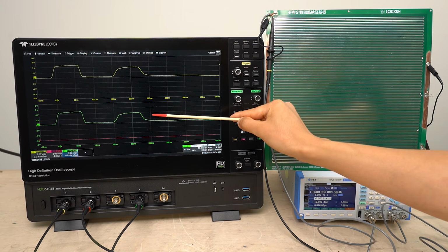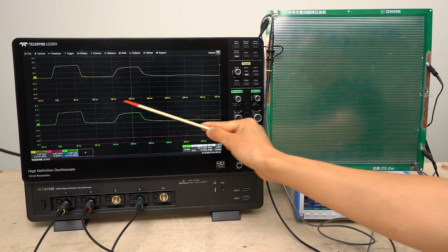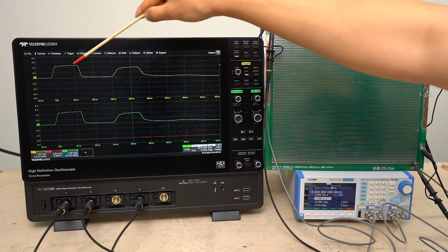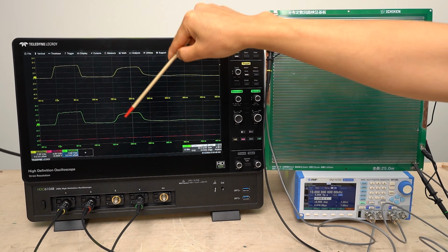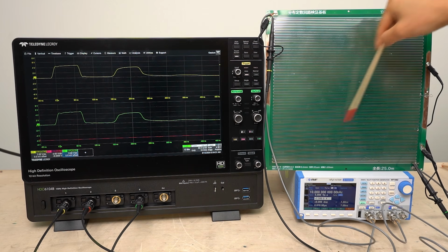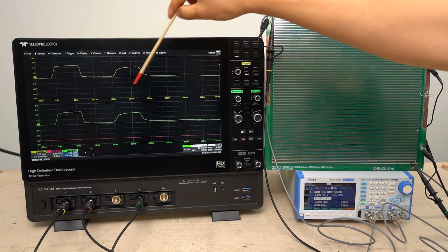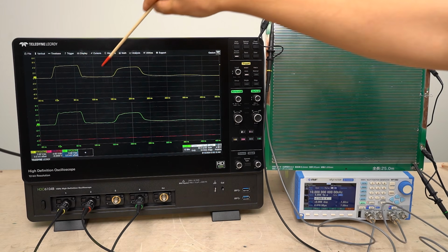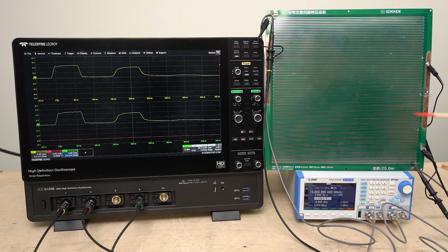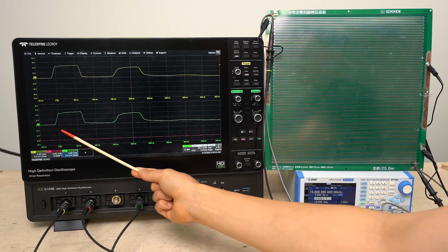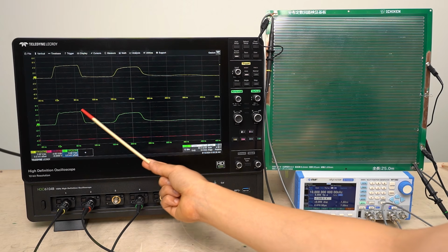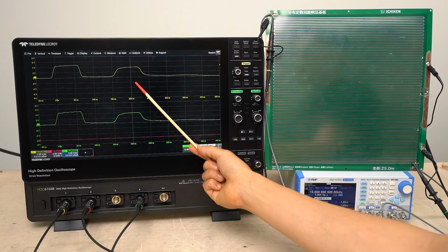Let me explain them in detail. First, the peak of the end terminal waveform. This is actually the pulse voltage from the input terminal that has been transmitted. As the voltage pulse travels along the circuit and eventually reaches the end, you can see it reflected in the waveform. Over here at the input terminal, we see another peak. This is the voltage pulse that was applied from the end terminal and traveled along the circuit. When it reaches the input terminal, this peak shows up. So, this pulse applied at the end terminal travels through the circuit and shows up here like this.